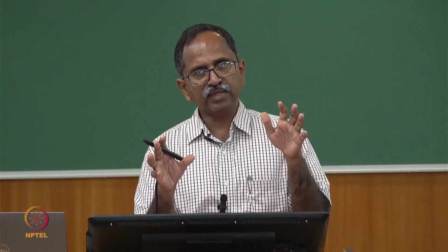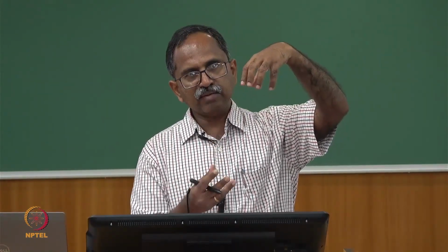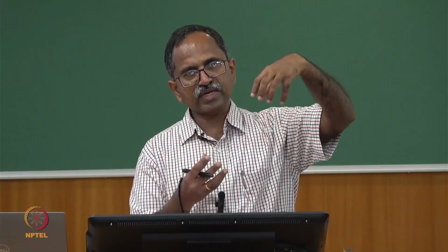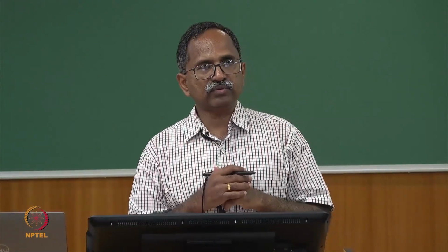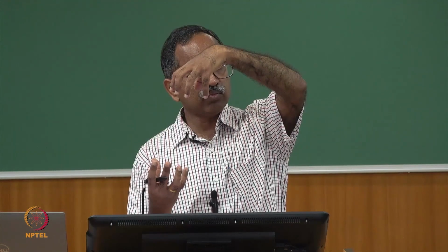What I mean basically is that had you pressed the first mass and second mass in the ratio of the first eigenvector, you would find that this term will be equal to 0 and the response will only comprise this particular part. Had you given one unit displacement to the anvil and the base was moved by minus 0.28 or whatever that value was, then it was corresponding to the second mode shape.